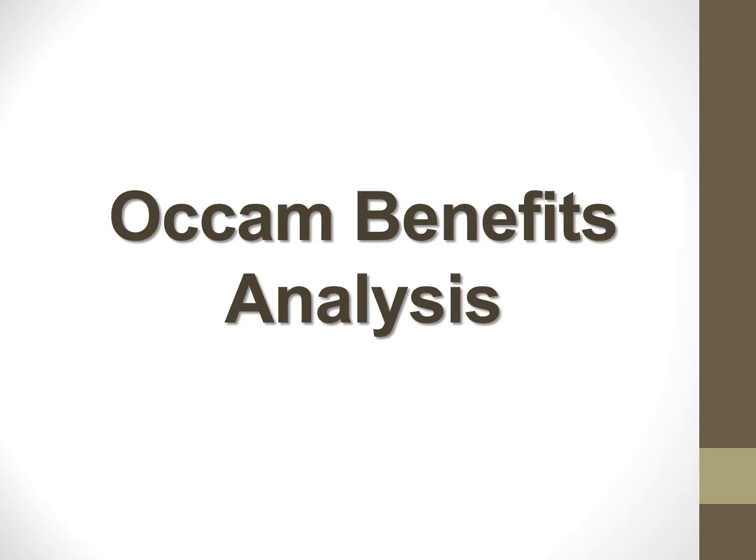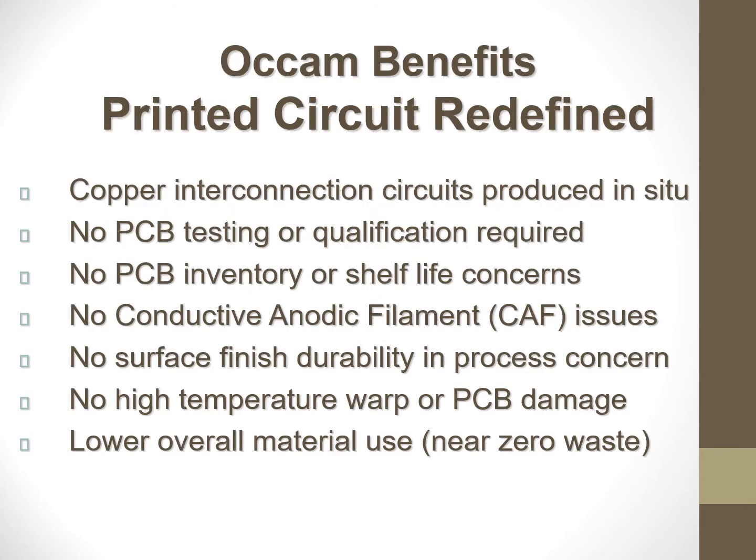So here's a benefits analysis for Occam, starting with the elimination of the printed circuit board. The interconnections are still required, but they're done in situ. So you don't have to have a printed circuit board and test it and qualify it. You don't have to inventory it. You don't have to go through concerns about shelf life concerns for its solderability. There's no concern over conductive anodic filaments, which are becoming more problematic as lead pitches come down. No surface durability concerns. You're not going to experience any high temperatures, which can cause components to warp or printed circuit boards to be damaged.